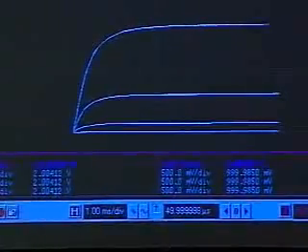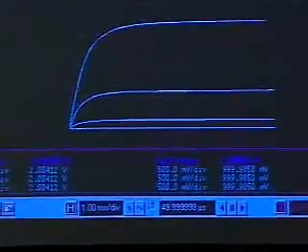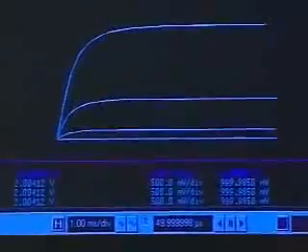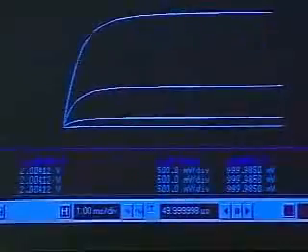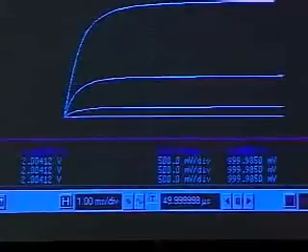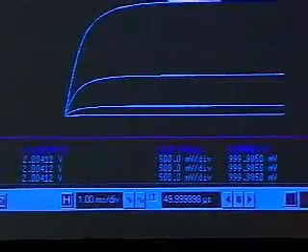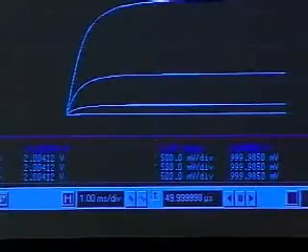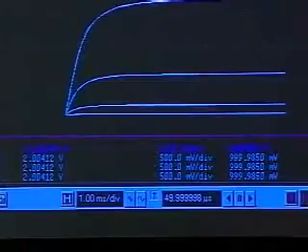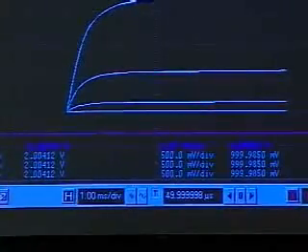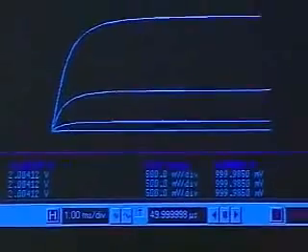This line up here corresponds to the output voltage, VO. What I'm going to do now, through some careful circuit hacking, is show you a load line and the bias point, and how the bias point can be moved up and down by changing the input voltage, which changes the corresponding output voltage. It's hardly visible out there.